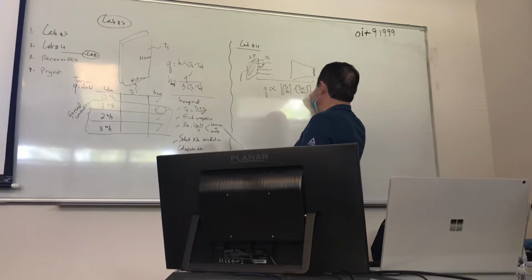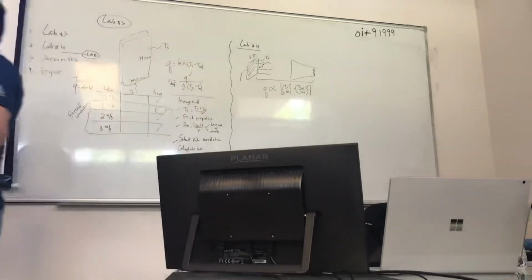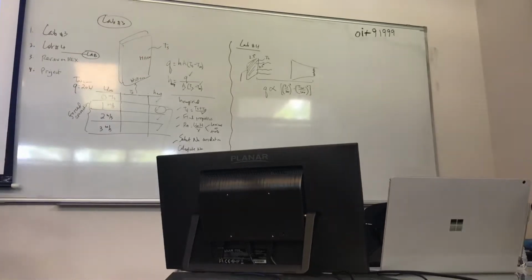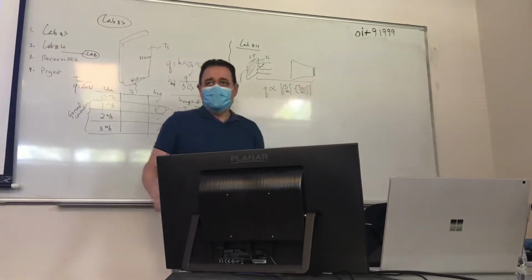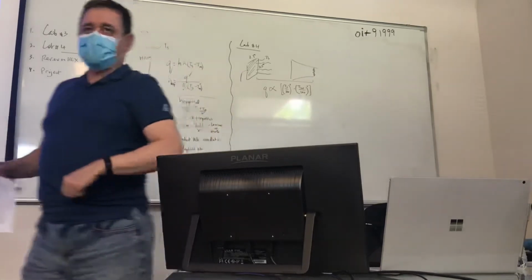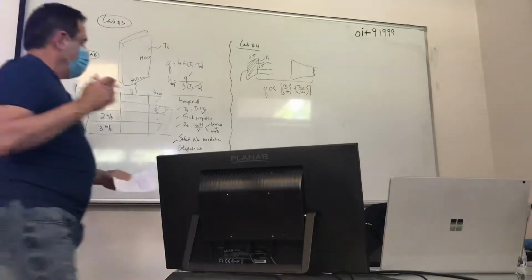and you go like, what the heck is that T over 100 comes from? It's really, I could have just said T S to the power of 4 minus T surrounding to the power of 4. In the lab manual, they just divide it by 100, because once you add 273, those temperatures become really huge, but it's really the same thing.